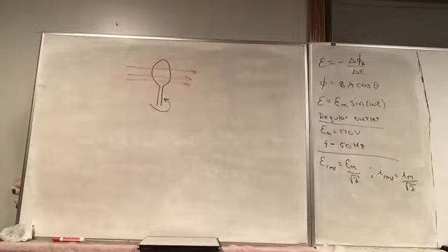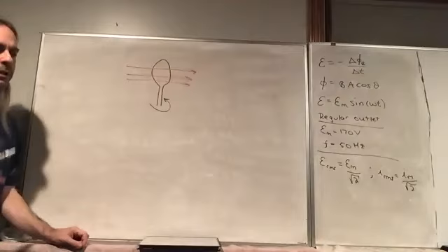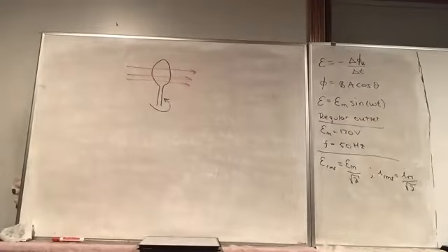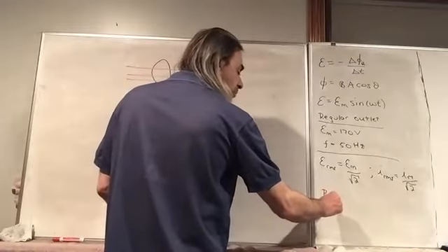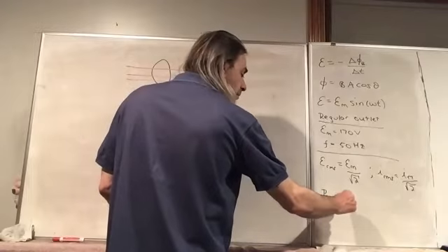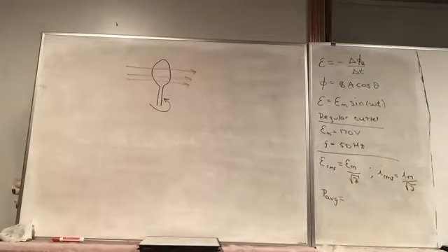Now, the power is going to fluctuate as well. But again, it's going through 50 cycles a second, so it's fluctuating very rapidly. You're not going to really see it going up and down, but it does. And so we can talk about the average power, where this is just a straight average, not an RMS value, because the power is always going to be in one direction.